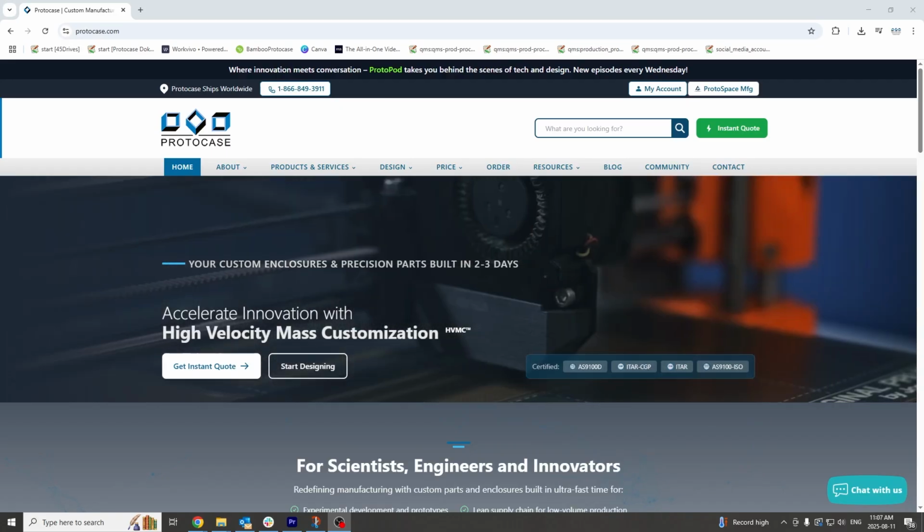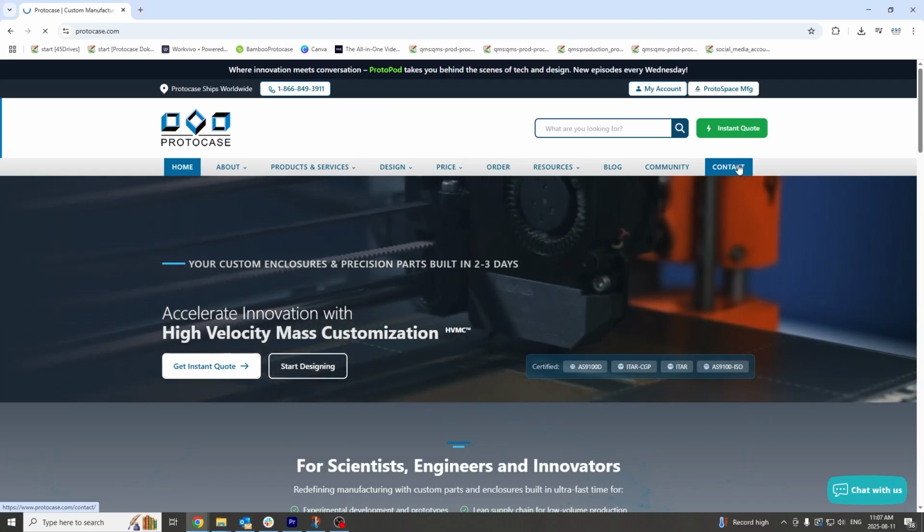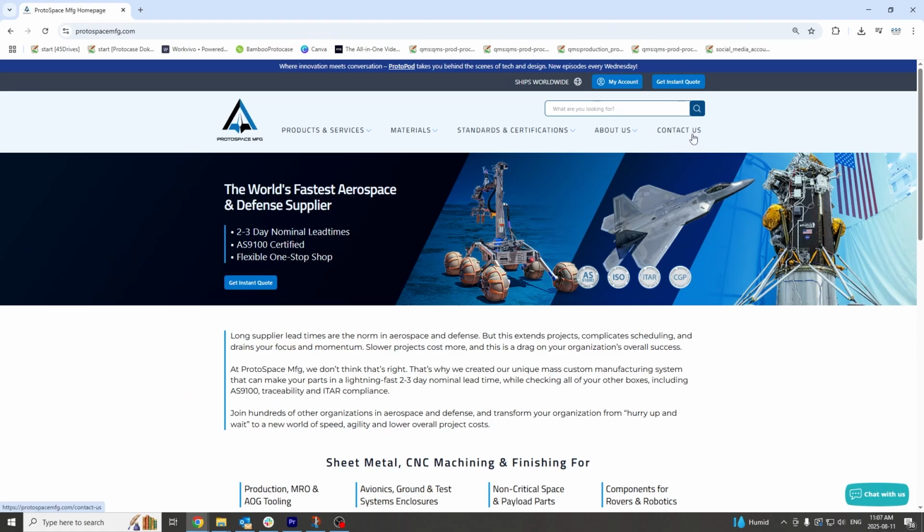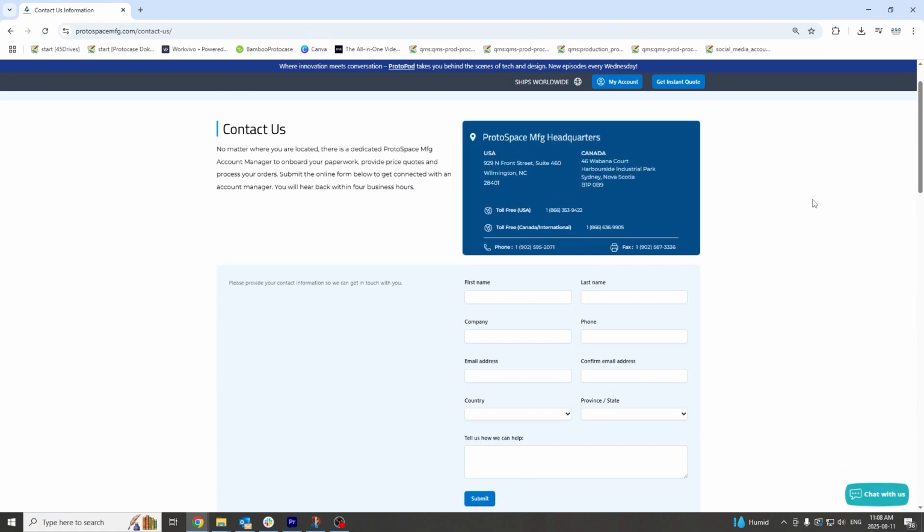If your enclosure is designed for a dry, climate-controlled indoor environment, the risk of galvanic corrosion is significantly lower. For parts intended for outdoor or marine use, consider designing for an IP rating with gaskets to keep the moisture out. If you have any questions about material selection for your custom enclosure, part, or panel, our engineering and design services team is here to help you make the best choices for your specific application.